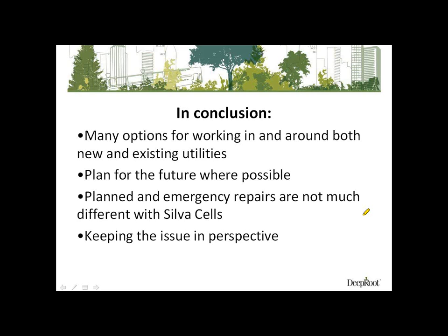And then you want to make sure that you run your geotextile fabric over the top, and you make sure you compact your subbase under the pavement, your aggregate. That's part of your pavement section.